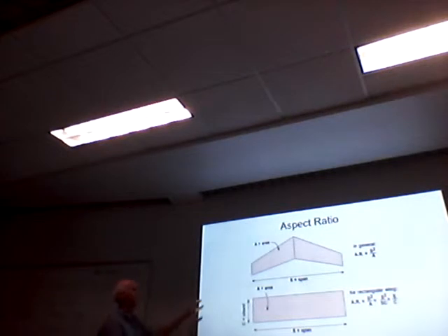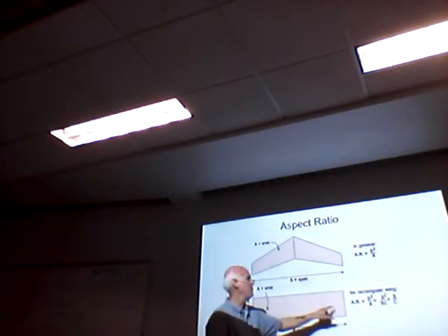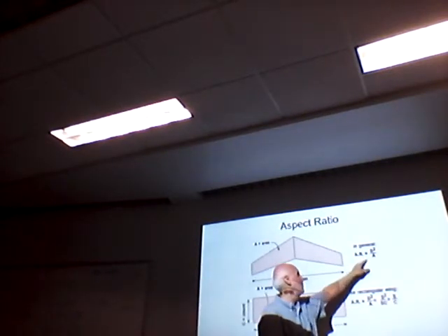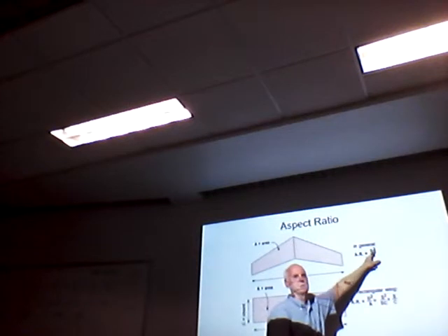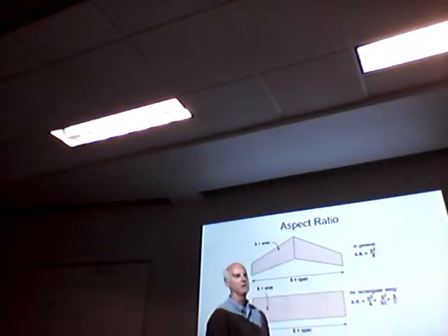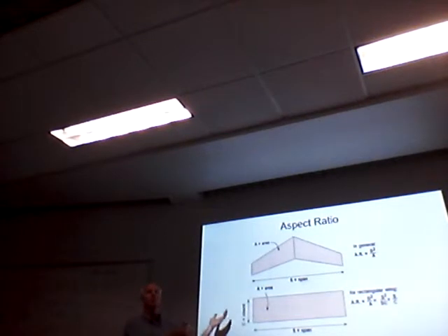Aspect ratio, remember the two things. So the simple thing, span over chord, or the more difficult one, span squared over area. And again, you're not going to be doing mathematics on this, but a multiple guess question would be derived there. Okay. You can see it. I wrote another note.